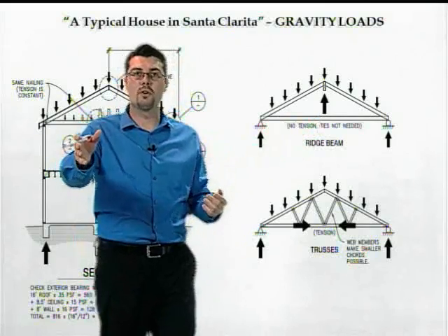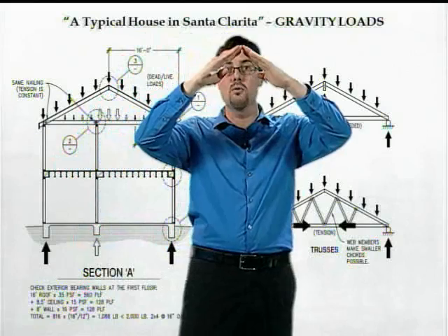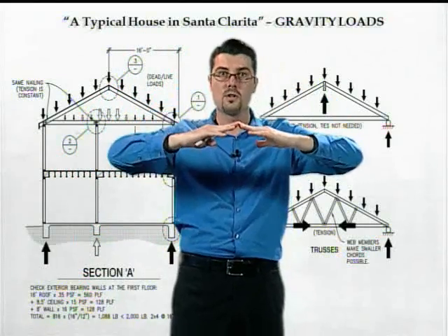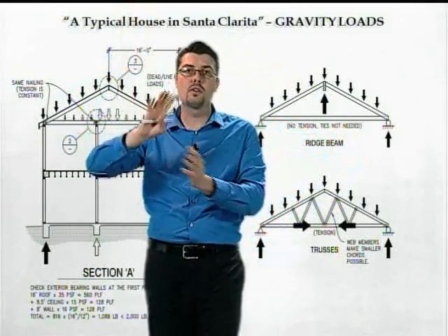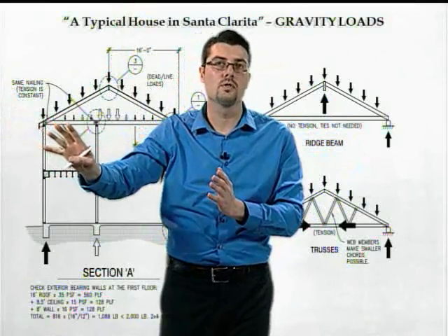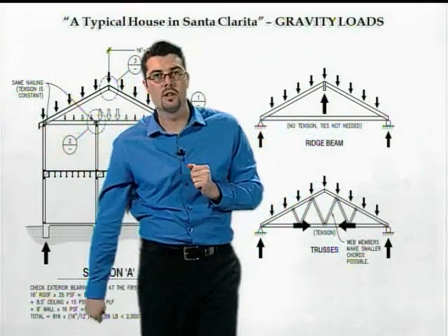So let's say you have homeowner A, who cut the ties in his house, had no ridge beam, and the roof starts to collapse. Another homeowner, if there was a ridge beam there, could have gone ahead and removed his ceiling joists, and it would have been safe because that ridge beam is what's supporting the load.